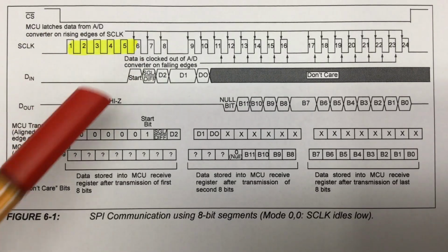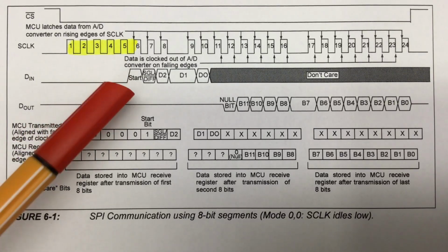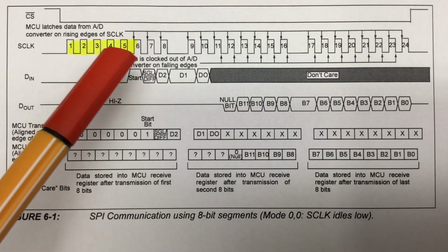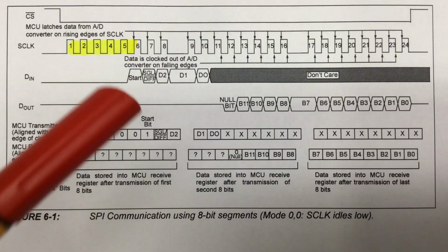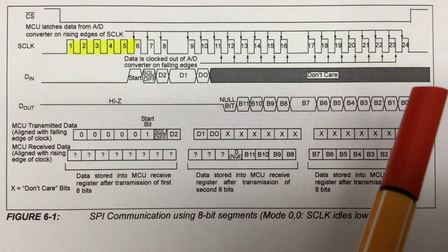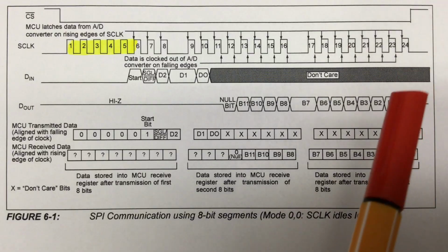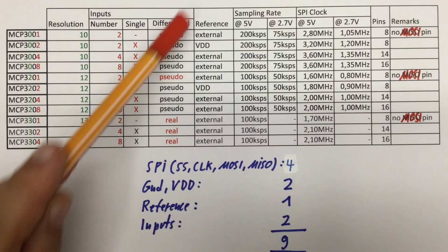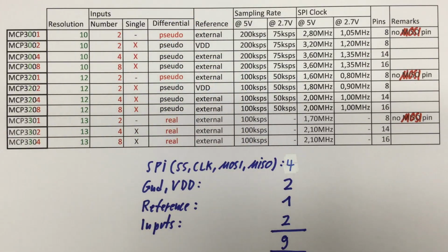The chip only really starts receiving the message after a high start bit, and I guess that's why they added that start bit to their SPI protocol. In that case, of course, our data is neatly aligned at the end of our bytes. Please note that with both techniques, you won't be able to reach the maximum possible sampling rate.